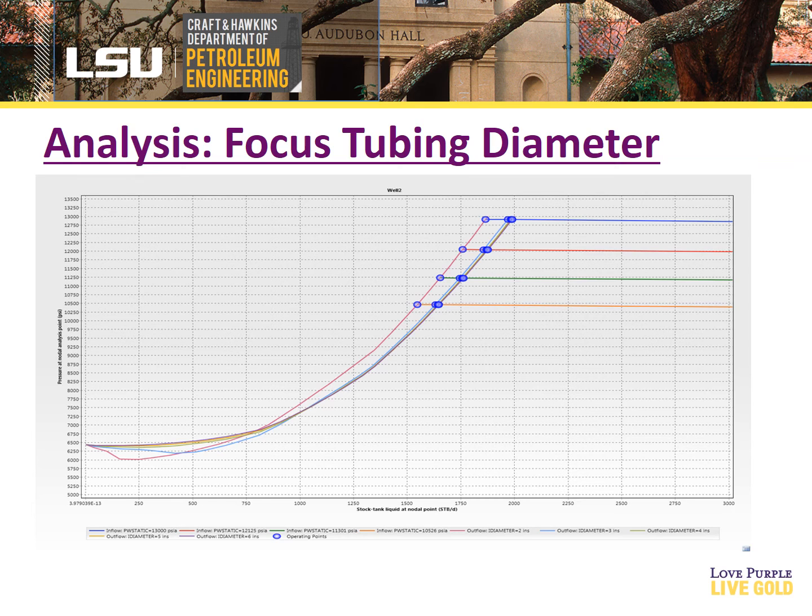As you can see, anything beyond 2 inches does not show great gains in tubing flow potentials. This graph also highlights the downward sloping TPR curve in the leftmost region, where the fluid flow is dominated by gravity, and then the upward sloping portion to the right as the fluid flow mechanics are dominated by friction.